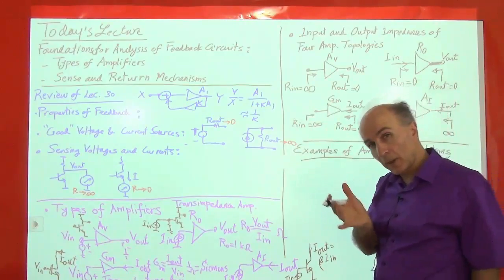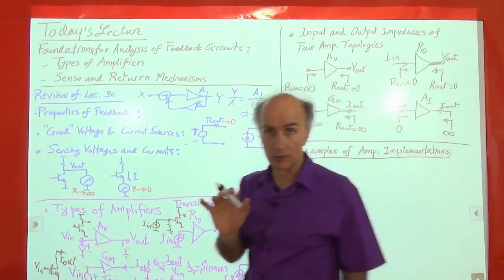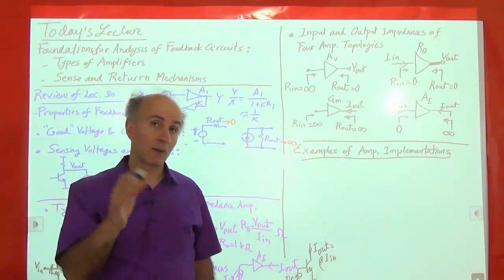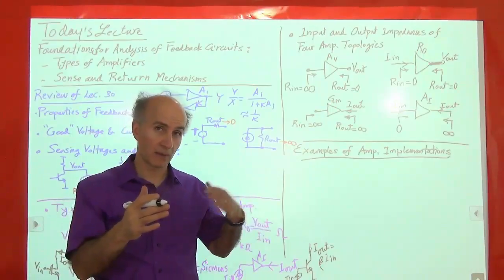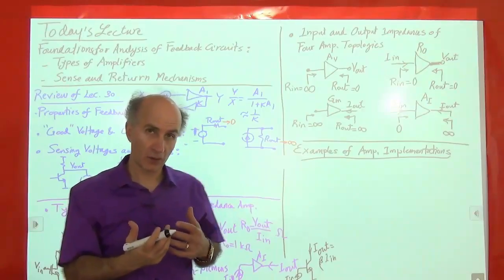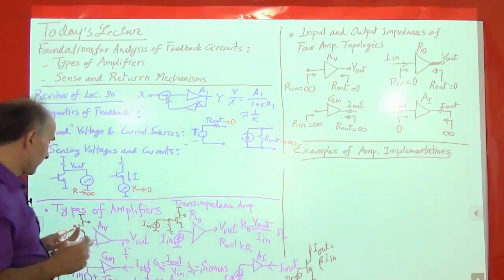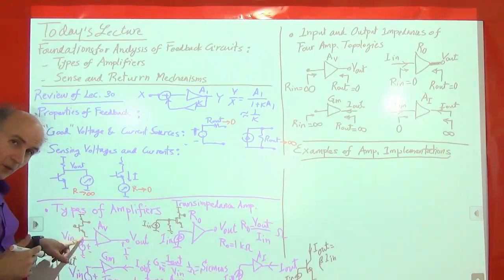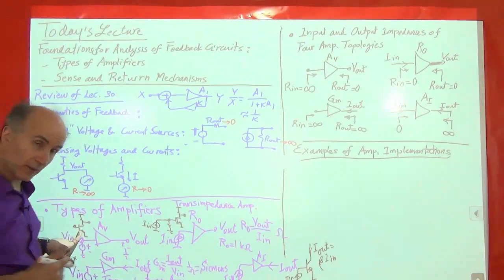So what kind of topology and what kind of transistor should I use? Well, a common gate or common base is no good because the input impedance is low. So I should go with a common source or common emitter stage. If I use a common emitter stage, the input impedance is R pi. It's not that high. So I should use a common source transistor.